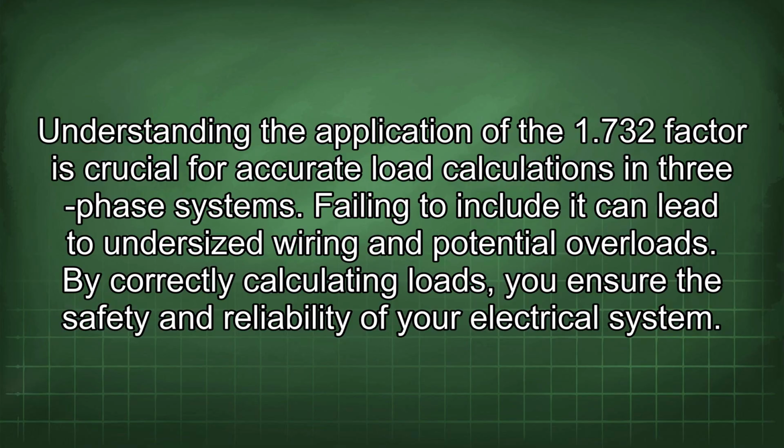Understanding the application of the 1.732 factor is crucial for accurate load calculations in three-phase systems. Failing to include it can lead to undersized wiring and potential overloads. By correctly calculating loads, you ensure the safety and reliability of your electrical system.